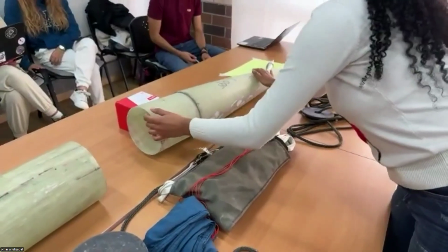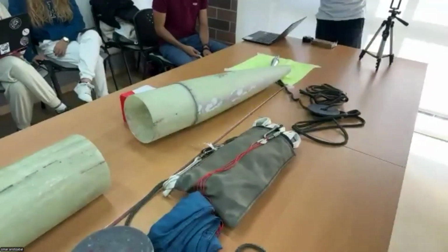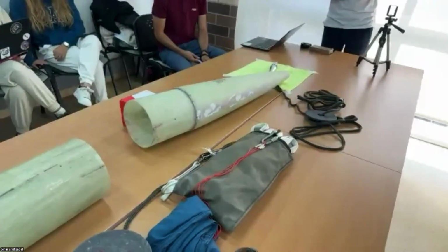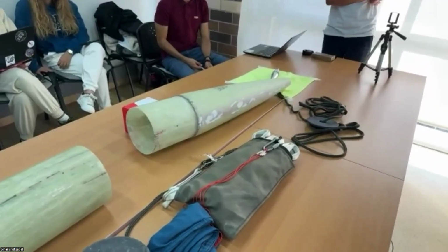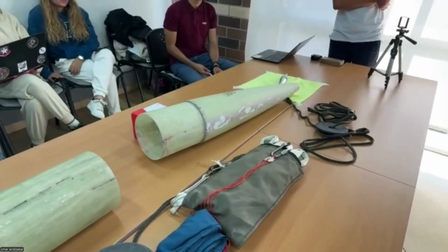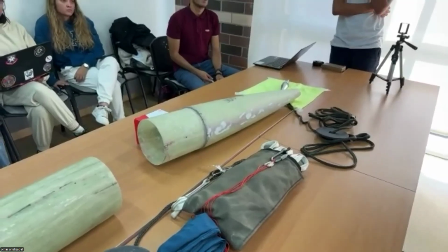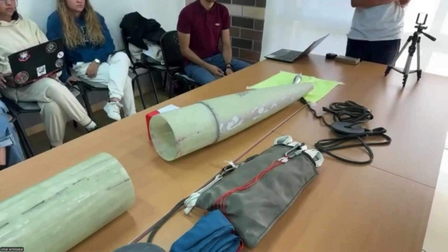Also, with calculations needed, the metric size is M4. Yeah, we are using 4 for both zones of ejection: the nose cone section and the bottom, the motor section. We are using 4 shear pins for each ejection event.